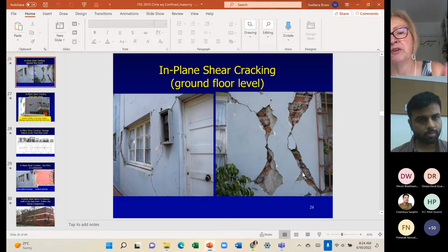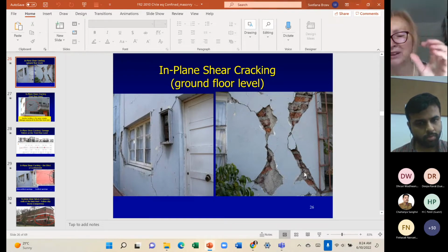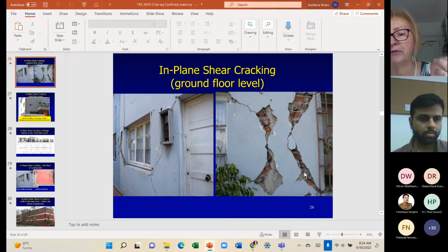If you know, when you have this location of the wall going, you've seen that red building in Kokenes, that's really, I mean, what to do there? The upper floors are okay, but the ground floor has such heavy, critical damage. It's so close to collapse that they vacated the building. But in this case, this is all repairable damage. I would say out of stages 1 to 5 of damage, this would be 3 to 4 maybe, but it could be repaired. Repairable damage.